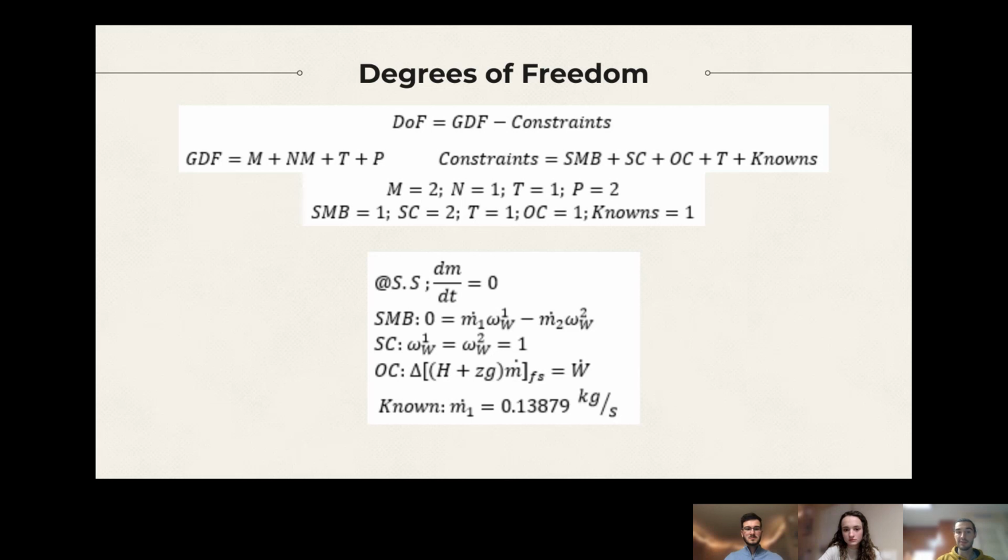So with respect to the general constraints, material balances, stream constraints, other constraints, knowns, and temperatures must all be examined. As previously mentioned, there's only one species and therefore only one material balance. This also comes into account when writing stream constraints, as the mass fraction of water in both is 1. Since the system is both isentropic and adiabatic, the total work done is directly related to the change in enthalpy. Thus, there is no change in temperature.